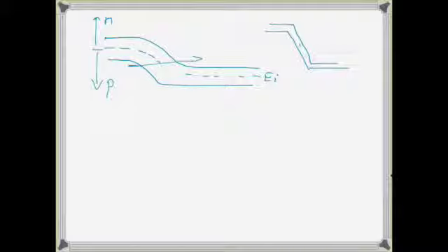Even in the regions where there's band bending, since it's a local calculation for each site, you're doing the same thing. So, as a function of position, the limits of your energy integral are constantly changing as you calculate electron and hole density throughout the device.